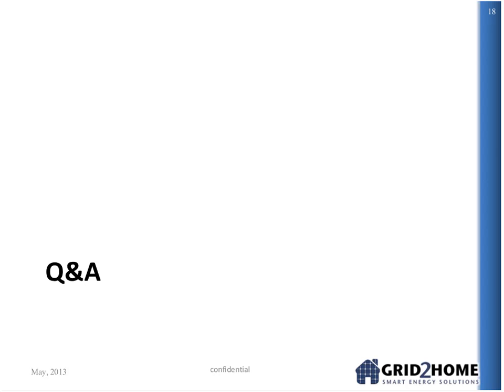All right. So I think, did we do this question? No, Hank. In scenario 1 with SEP2 cloud server, where do the HAN client devices host their SEP2 resources, the cloud, the ALG, or elsewhere? With SEP2, with function set assignments, they can point to the cloud or to the ALG. So it's really down to where you want to host them.